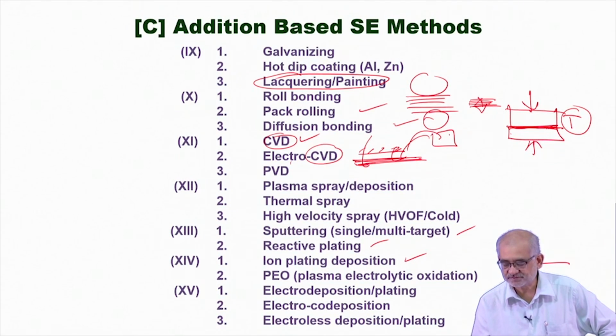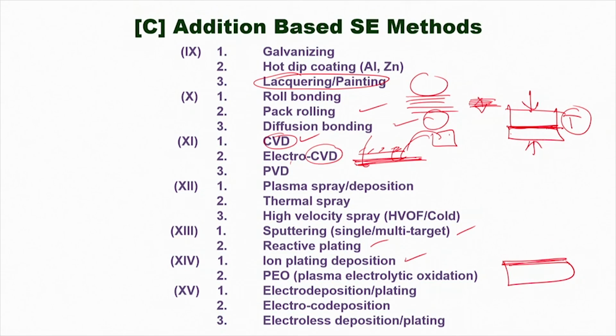So, you take a substrate and then you allow selective oxidation from the surface, so that these metallic grains get selectively oxidized, and this oxide and the metallic substrate below are fairly compatible. So, there is no immediate decohesion expected or anticipated.